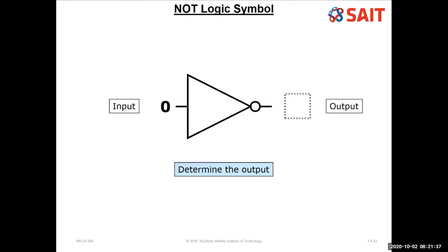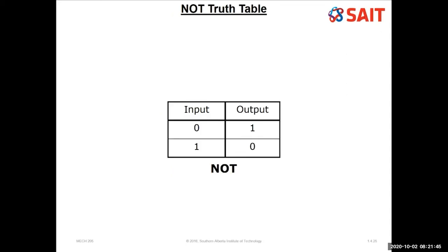So if I have 0 in, of course I'm going to invert it. There's only one possibility. I must have a 1 output. 1 input, I'm going to have a 0 for the output. The simplest of truth tables: a 0 in and a 1 out, or a 1 in and a 0 out. That's an inverter. If I had a 0 in and a 0 out, a 1 in and a 1 out, we often call that identity or a buffer. It's not making any changes at all.